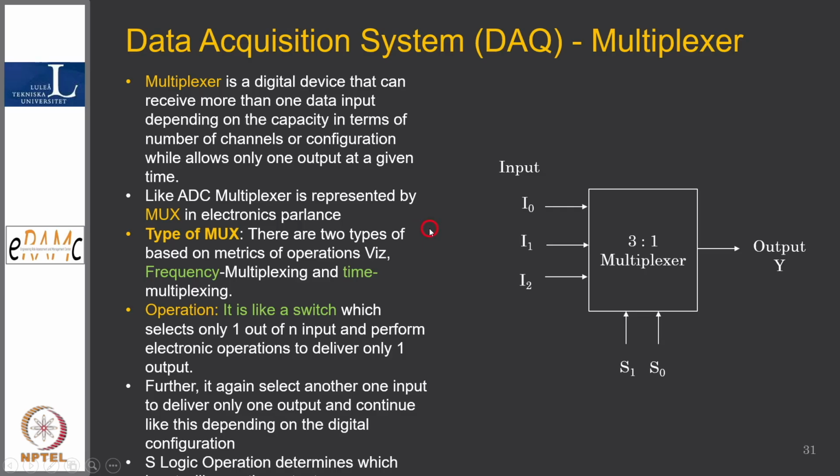Now what we are doing is the same thing, and we are automating it. From his experience, we know that the two peaks come close by, and their amplitude is what our expert opinion had said, and we are getting that. So it is an inner race failure. That means it is a non-intrusive technique. Without opening the bearing box, you could tell and you could prepare the maintenance plan.